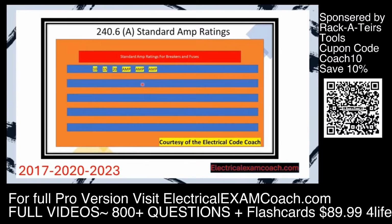The reason that this table is so important is it unifies the entire electrical industry. The manufacturers make these size breakers. The stores stock these size breakers. Installers purchase these size breakers, and when we are doing our load calculations in the NEC, these are the sizes that we're actually going to use.